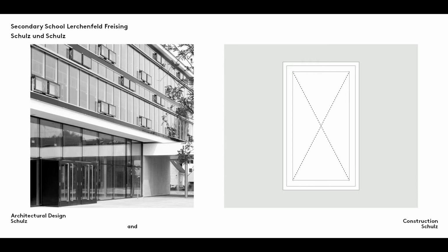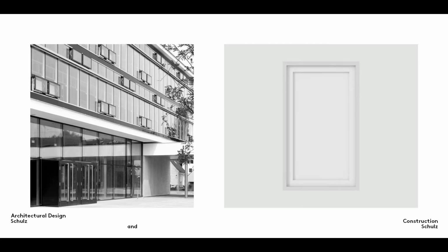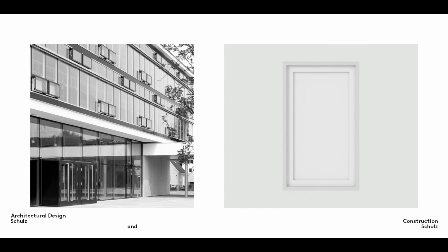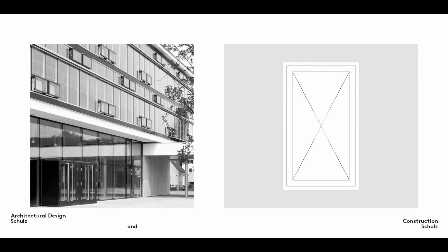Curtain wall parallel opening windows were much in vogue a few years ago, but are now less common. These windows open outwards parallel to the window plane thanks to scissor-type hinges. They're indicated on elevation drawings by means of a diagonal cross.